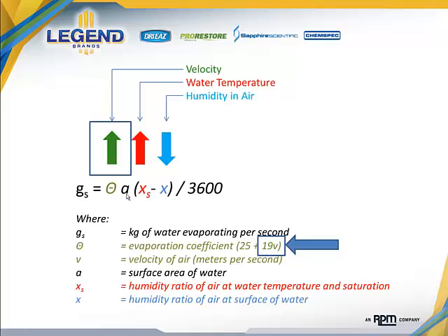And in this expression, it is a multiplier of the other factors, namely the amount of moisture in air, the amount of moisture in the material, and the vapor pressures associated with those. What this tells us is that the movement of air across a wet surface has a dramatic impact on the ability to remove water from a material and that surface.